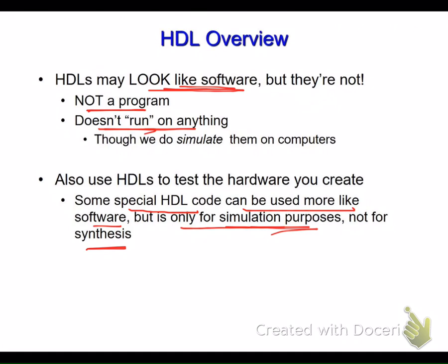What you will download over the hardware is your design, but the test bench will be in a process before the download. The hardware verification will be after the downloading, but this does not have anything to do with the test bench that will be written in order to test the design of the FPGA. In the hardware, you will design the whole design. Of course, you will have an oscilloscope, you might have a function generator, you might create some of the signals from the computer. You can send them through the serial or USB port, and then read back and so on. This is another thing. But I'm speaking about the test bench that you will write in Verilog.